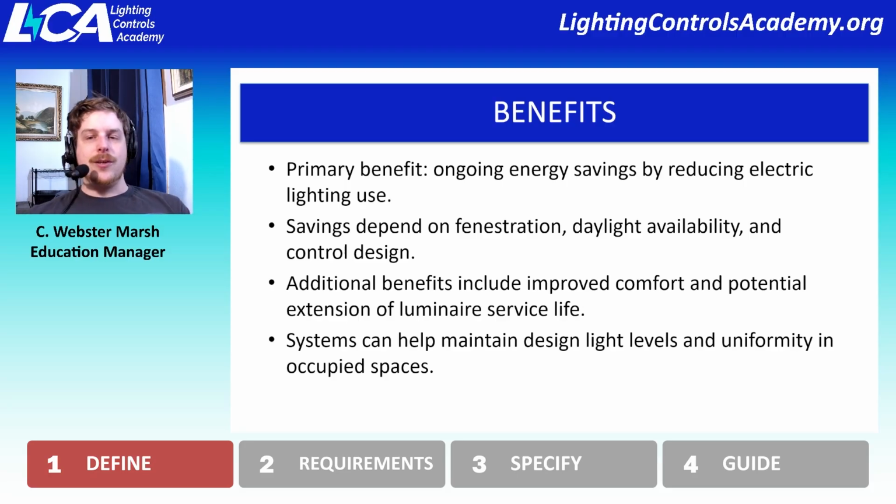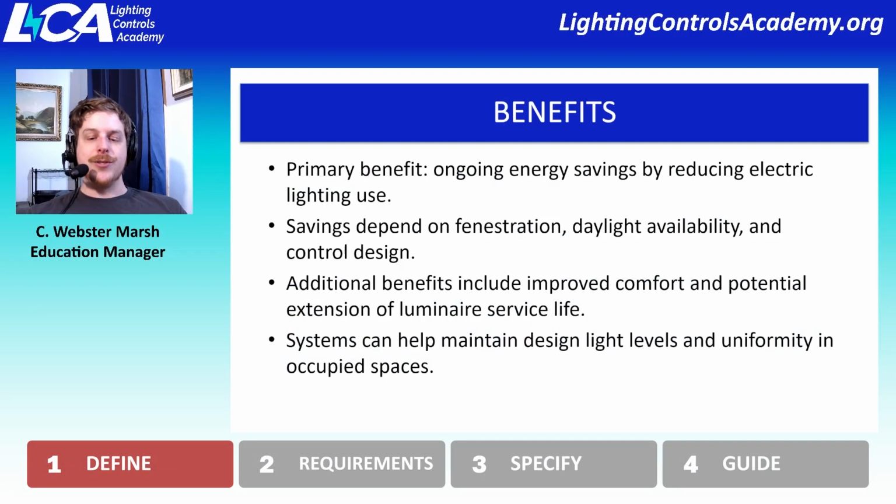And additionally, we want to make sure that things are comfortable and uniform. If there's a lighting designer involved in the project, they are going to make sure that their electric lighting is hitting a target foot candle or lux level on a task surface. And a good daylighting controls design is actually going to try to maintain that level under all circumstances when daylight is involved. So having that daylight detection method and daylight responsive method is actually going to work towards the benefit of the lighting design.